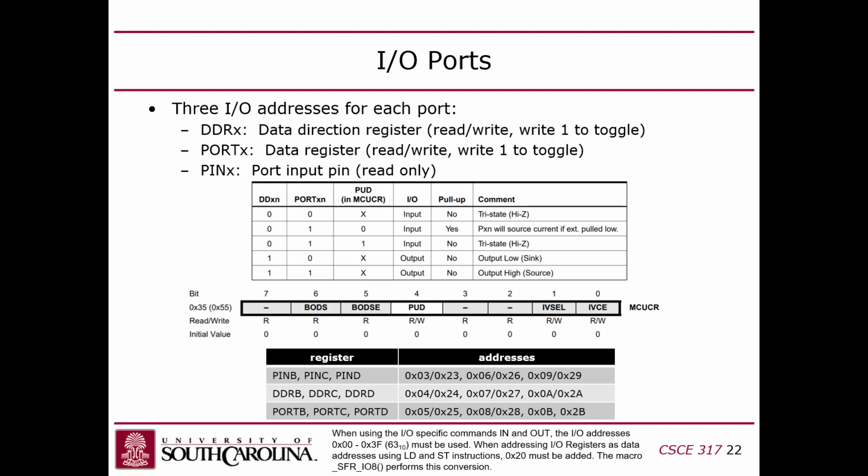Yes? Is this something that's done at the beginning of the program? Yes. Well, it could be either way, but for example, your code might have an initialization section that sets all this up, or you could change modes halfway, while you're running. I think it's most common probably to set things up at the beginning. So every program will have its own setup at the beginning. I would guess it's uncommon to change the GPIO setup midway, but it's possible.